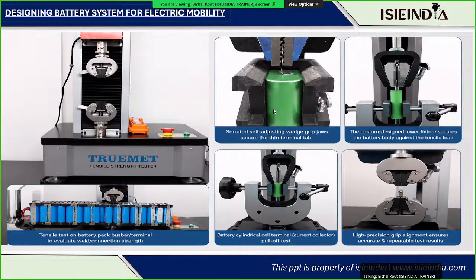These systems continuously capture high resolution images during manufacturing and compare them with a predefined standard. The machine checks battery cell dimension, polarity orientation, weld quality, alignment accuracy, any missing component, insulation placement, and assembly defects in real time.